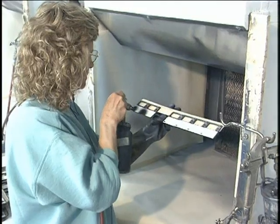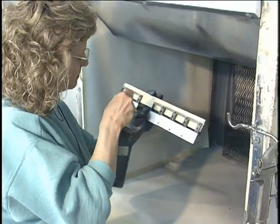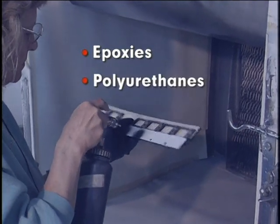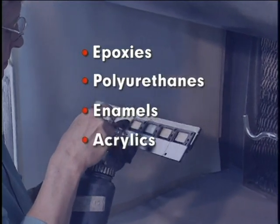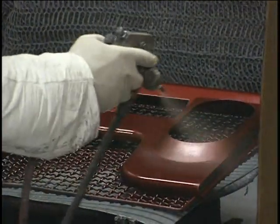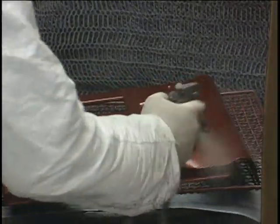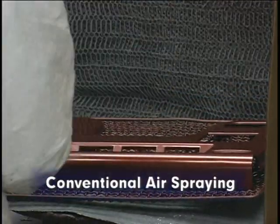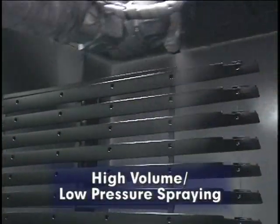There are a variety of paints available for use on plastics, including epoxies, polyurethanes, enamels, acrylics, and latexes. Paints are applied to plastics using many methods, with some of the most common including conventional air spraying, high-volume, low-pressure spraying, and flow coating.